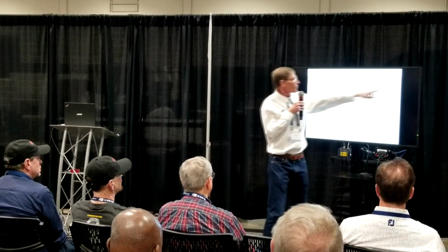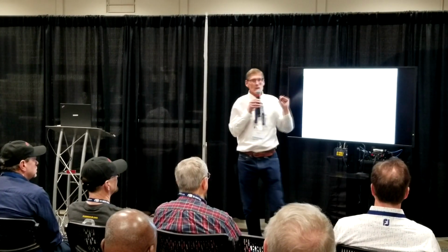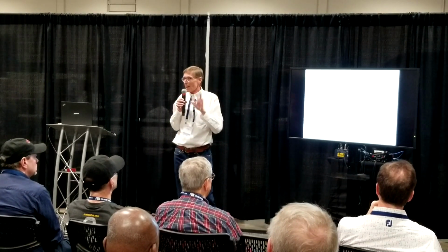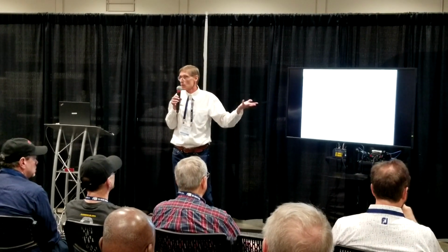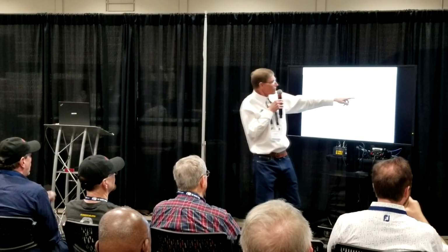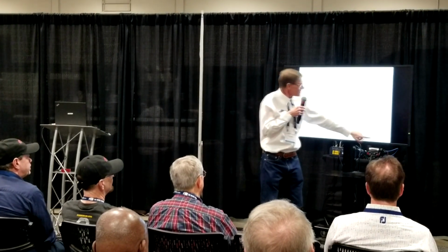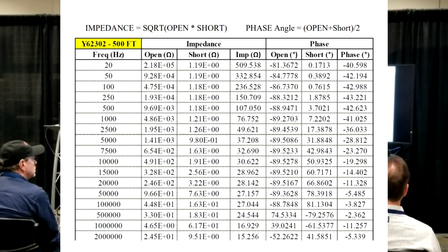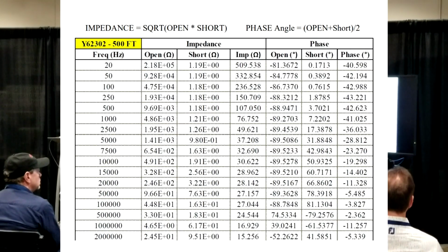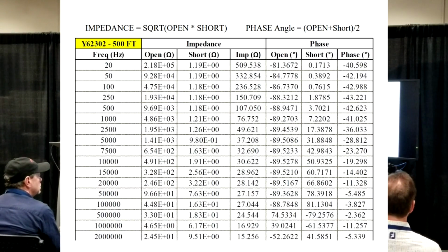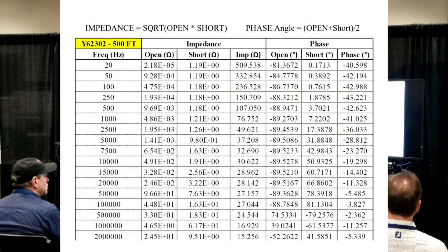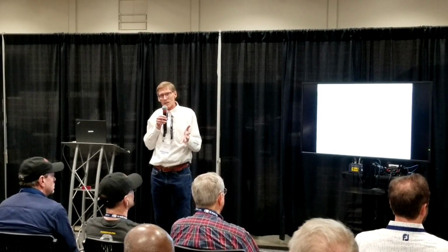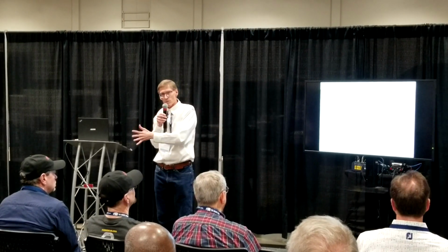No, we're not. We're at minus 40 degrees at 20 hertz. Not quite 0. If you get down close to 0, it's going to want to go to minus 45 degrees, which is a capacitor, basically. In other words, our cable is a long capacitor. As we go up in frequency, all of a sudden our phase is getting pretty close to zero. Those graphs said it should, and it is. These are real measurements off real cable. This is not a theoretical guy with a calculator sitting at a desk. This is real measurements on the stuff we use every day. So we see that it matches the theory. We're starting to get very resistive as our cable goes up in frequency.